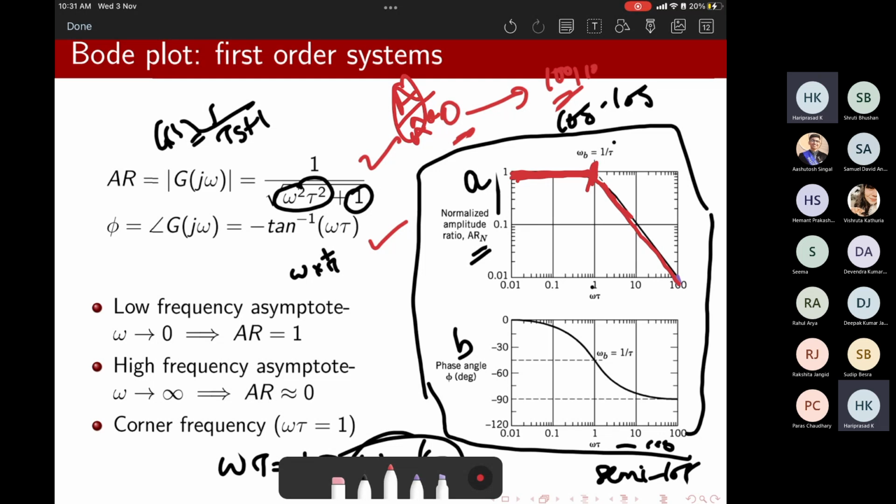So by looking at the corner frequency and the related points, you could come up with a stable operating regime. If you would not like to do any experimentation, you can just take this inference. Till the corner frequency, whatever you do to the system, it is not going to do any harm. If you are doing any experiment beyond it, be careful.